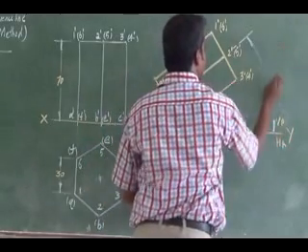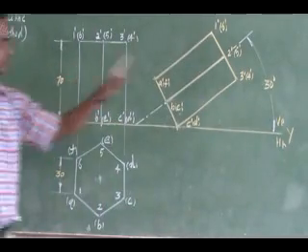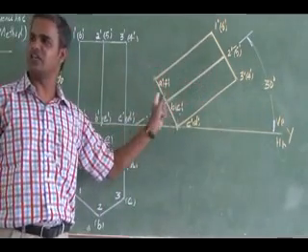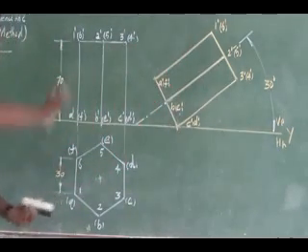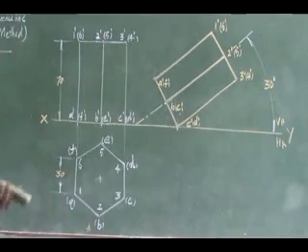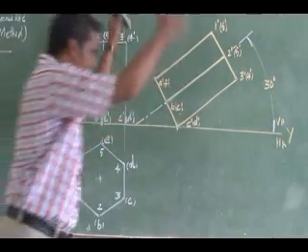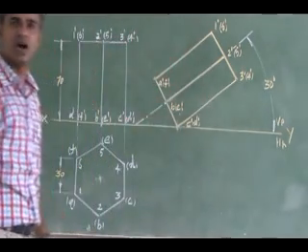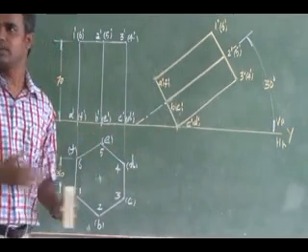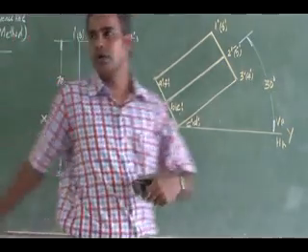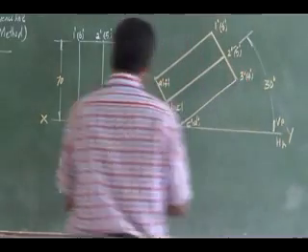The axis here is 30 degree inclined. So for the axis 30 degree inclination, I have measured 60 degree of the base, then I have redrawn it and reproduced this front view. This is nothing but the change of position. Now to proceed for the top view, similar to your projection of planes, you project all the base corners from the front view and from the previous top view. You will get the intersection location. You mark the intersection location. Just I am projecting.